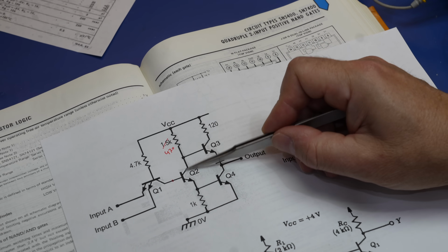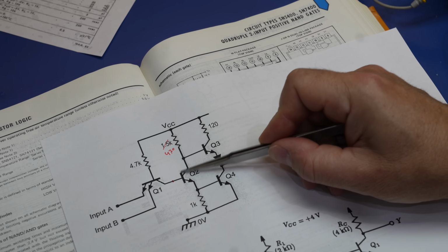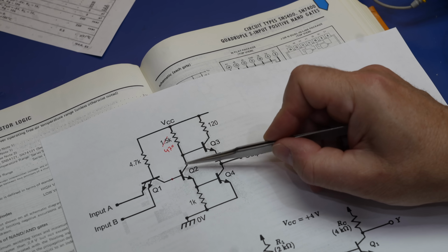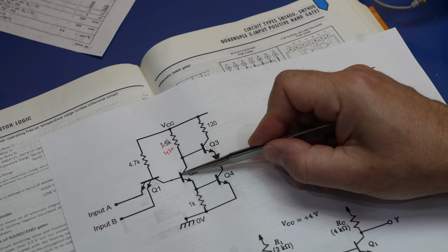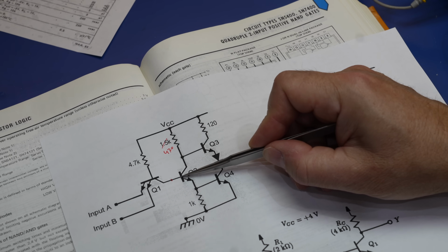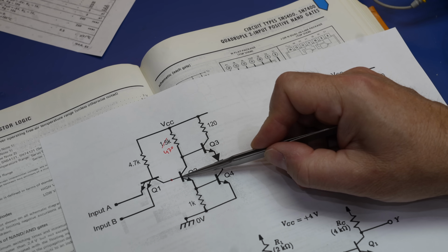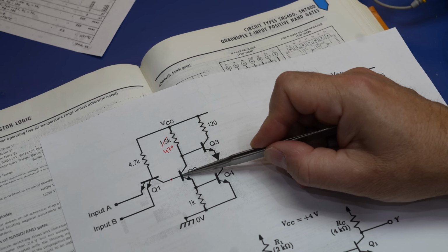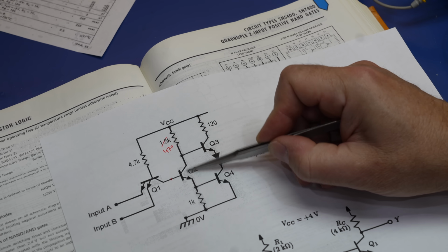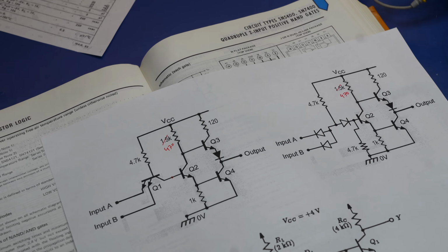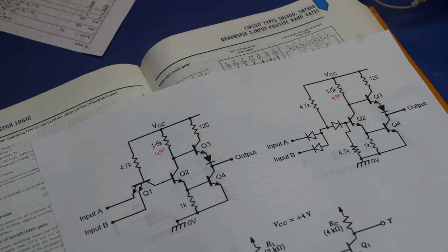Also, that's not a valid explanation, because in a transistor, the PN junction between the collector and the base doesn't behave like a diode at all, so it means absolutely nothing. But what happens is that there is a ton of carriers in the base, and now if you want to get the transistor out of saturation, you have to get all the carriers out of the base before the transistor shuts off. It takes a while for the transistor to turn off. Sorry guys, I'm foolishly trying to explain this without elevator music and tripping all over myself.